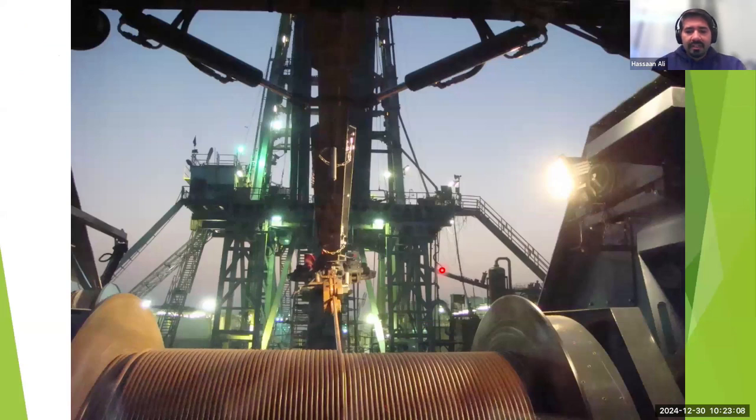This is the view from inside the land acquisition unit. So you are sitting on the winchman seat, and you are seeing the wireline drum. This is the device that is measuring the cable tension, and it is also measuring the depth of the well. Effectively, it is using how much cable you have used, and from there it is correlating it to the depth of the well. And this is your rig floor. This is your derrick, and your wireline cable is being run through this device, going through the sheave into the drilling rig.